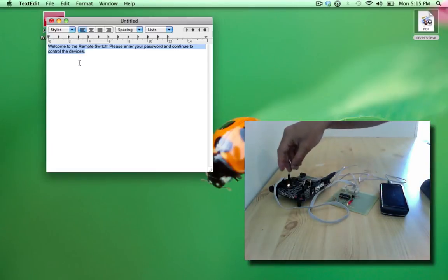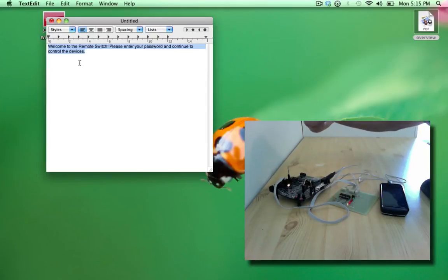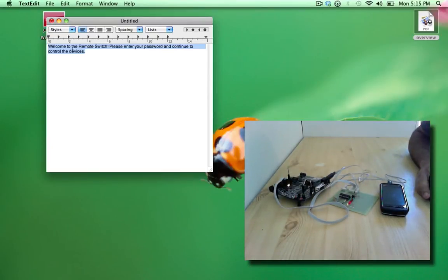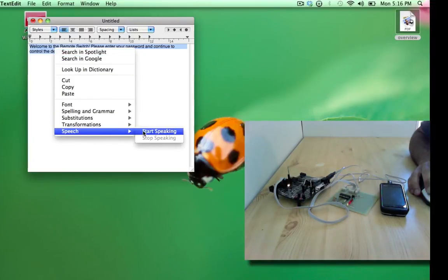So as I told you, this jumper emulates the record button. You will see that as soon as I emulate the press of this button, a red LED over here will start blinking for 5 seconds, which indicates to the user that the recording is to start in 5 seconds, and then it will stay bright for 7 seconds. During that time the microcontroller will be recording the welcome message into the flash. So I hope I synchronized things well.